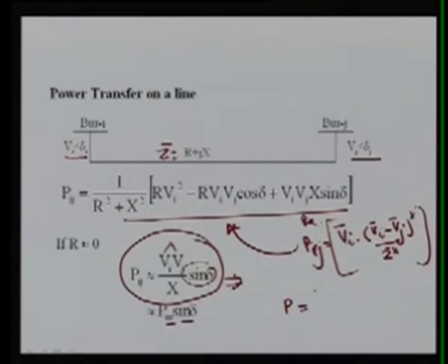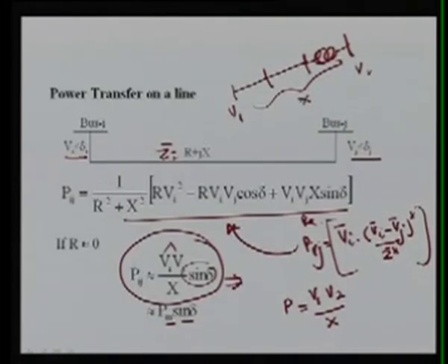Node means bus. Here is the voltage of one bus, the voltage of another bus, divided by X between these two buses. There may be several elements, for example one line here, another line, and some transformer and then another bus. If you are tracking V1 and V2, the whole X will be the total of line 1, line 2 and the transformer.